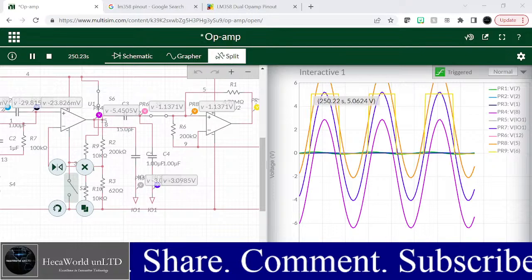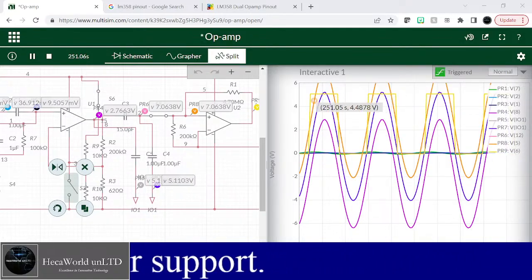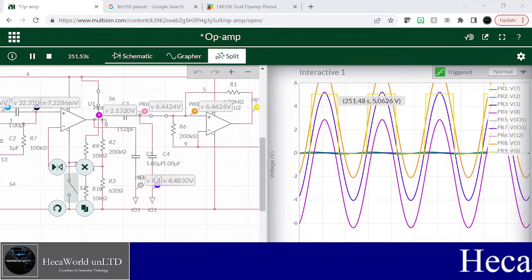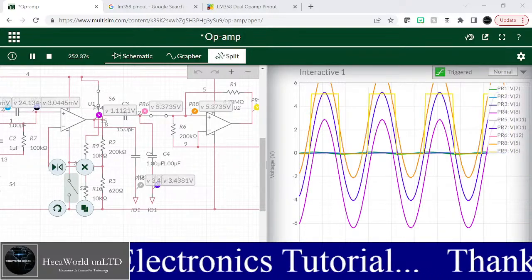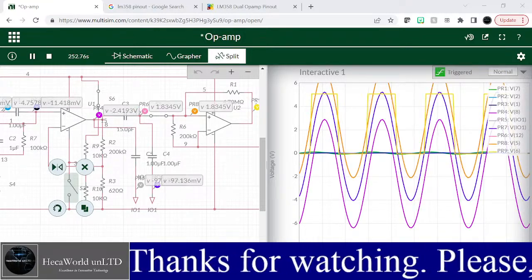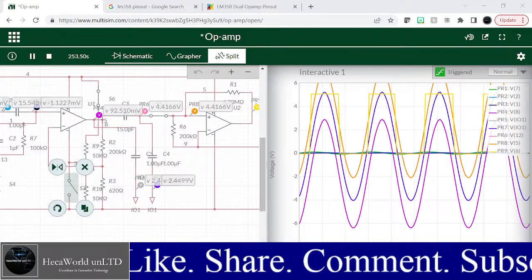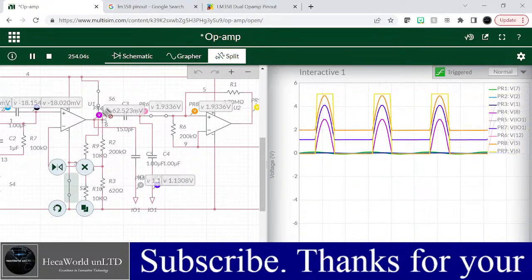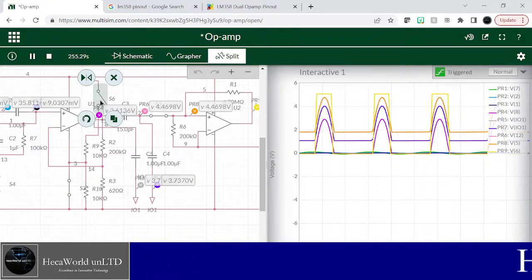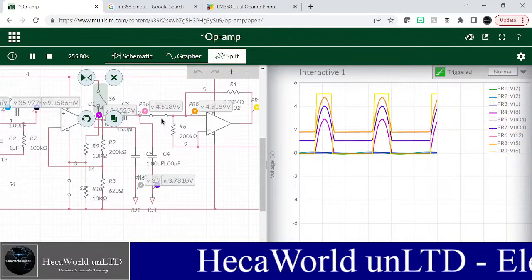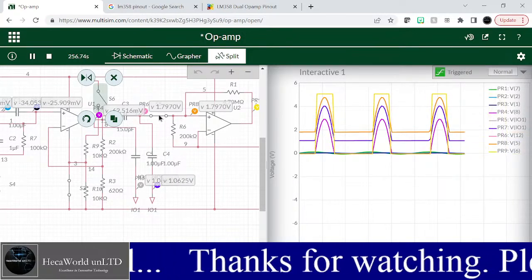Now you can still see our Schmitt trigger is still working. So we're going to build this circuit. The Schmitt trigger still works, and then the audio signal will be coming out as a full sinusoidal wave. Now there's a reason we put the switch here. I'm going to flip the switch open, but before I do that, I'm going to return the circuit to the original design. So pin 4 goes to ground, and this resistor really wasn't there. So when the switch is flipped open, it wasn't there. So I'm going to turn off this switch in the middle here to see what happens.